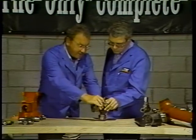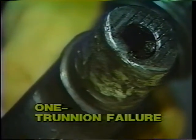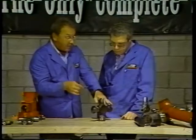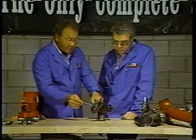Now, you can see how the trunnion of this U-joint has become discolored and corroded. Notice how only one trunnion is bad. This is known as one trunnion failure, and it's caused when you don't thoroughly purge all four seals when lubricating the U-joint. Now, eventually, the bearings are burned away. If the joint is purged properly, you'll see lube out of all four seals.